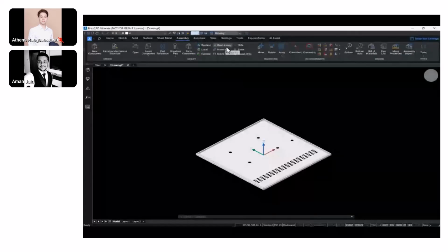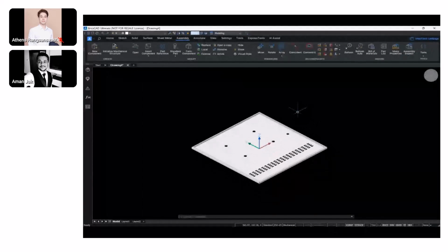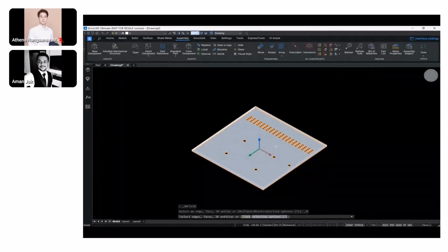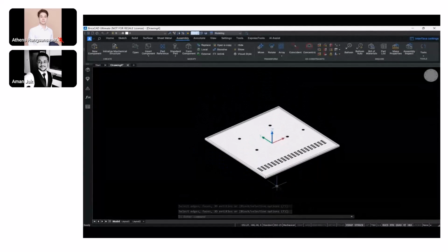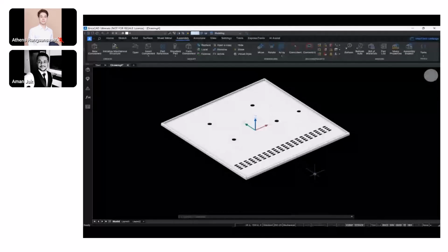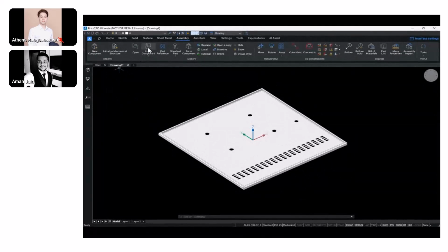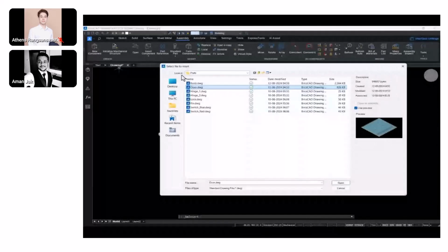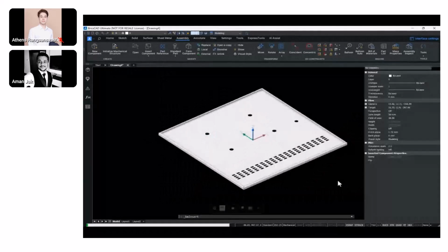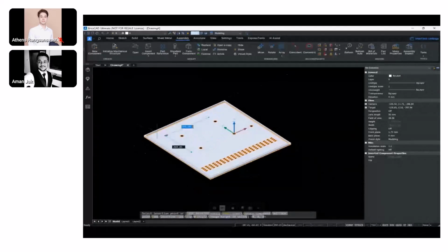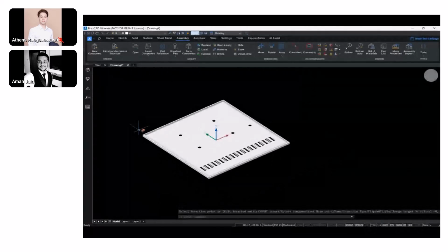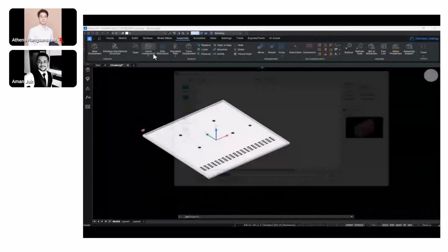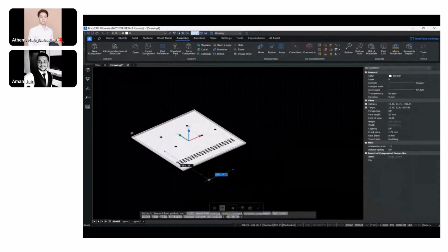And I'll just change the representation to modeling. Okay, and then I have some additional components in place which I'll insert. In BricsCAD, since it does not differentiate between a part and an assembly through an extension, they are all DWGs. I can simply insert a component using the BM insert command, and this is the one that I want to insert. So these hinges would essentially be on the door, and then we have a separate hinge for the body as well, which will mate together to create our complete enclosure body. Right. So we add two instances of it.